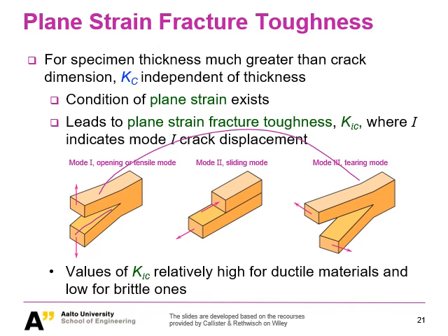That's why we need to specify what kind of fracture toughness we're talking about. That's why when we talk about the Kc value, we always try to indicate before the C the Roman number 1, 2, 3. So don't read it as KIC. It is K1C. So this is the mode 1. So that is the most often used mode or tested mode for fracture toughness.